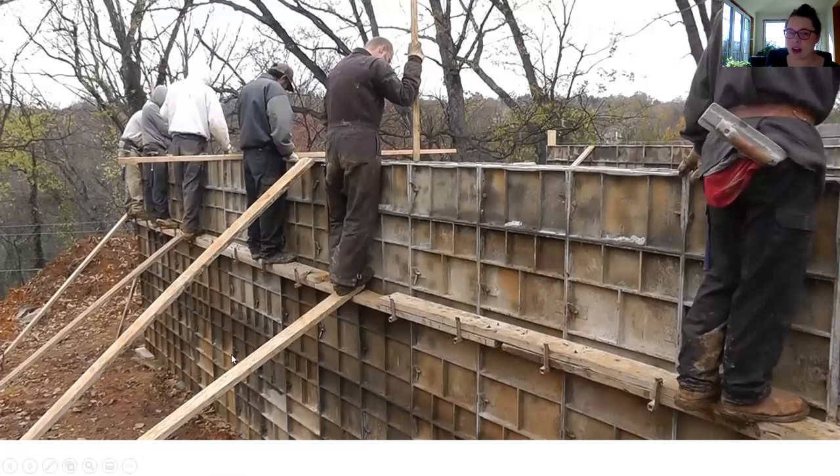We'll look at bracing. You need bracing in order to hold things in place because concrete is quite heavy. If you just put the concrete in without bracing, the force pushing down, we call that hydrostatic pressure, would push the forms out. So you have to have bracing to compensate for that. So we'll look at how we calculate those different pieces.